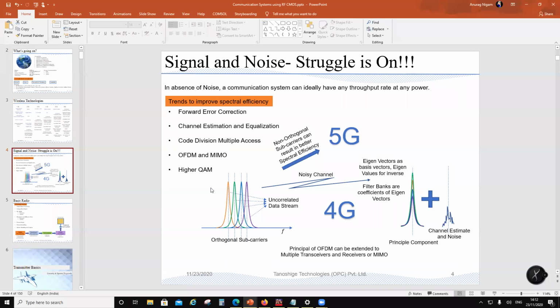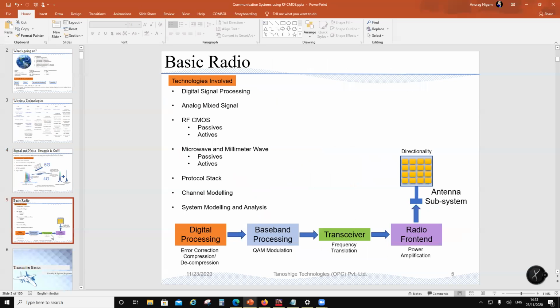If you are having a very high data rate and you realize that the bit error rate has gone up, you can fall back to, let's say, QAM64. If you still realize that your bit error rate is very high, you can fall back to QAM16. So it really depends on the channel, and the system can adjust. The PHY, the physical layer, is supposed to support up to QAM256 in 5G. So that's what that is.